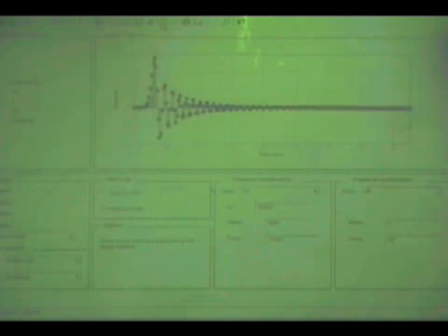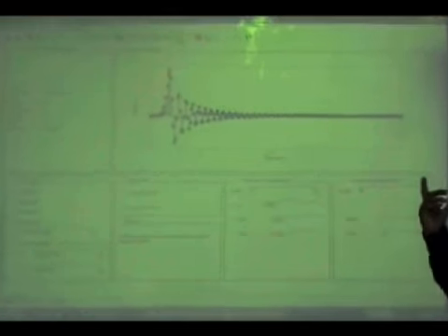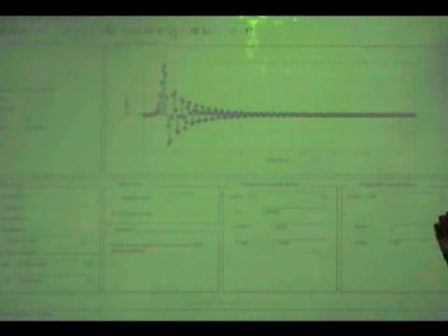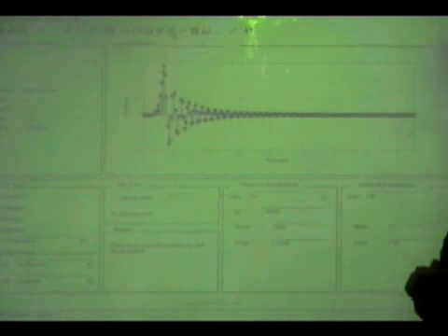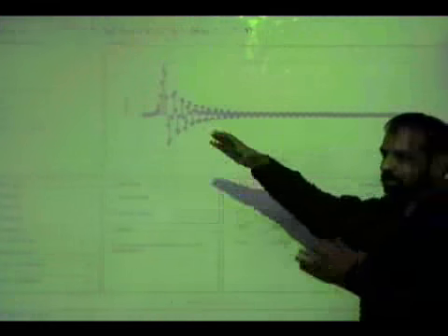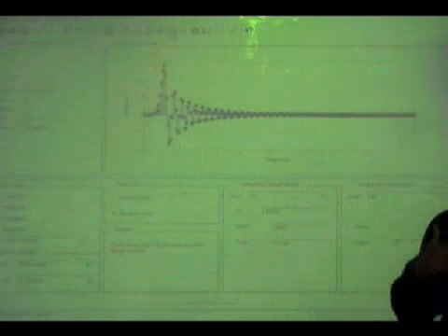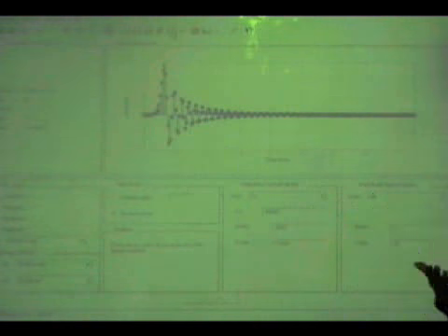It is an infinite impulse response system having 31 exponentials in it. If you put all the exponentials together, this is what you see. Otherwise, no significance as such. You will not make out anything, but just for completeness, though you cannot really plot it to infinity, they have plotted it, and it will be decaying. Anything which is stable will have a decaying impulse response. So it's a decaying impulse response.